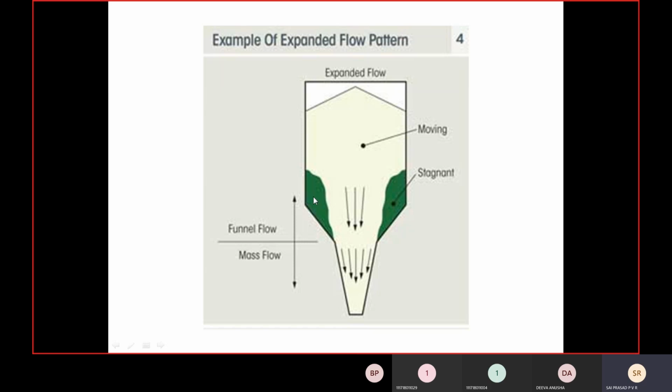If this angle is more, what will happen? Then the holding capacity of the solids in this particular region decreases. Suppose this line is like this and here you have an opening. At this point we will hold some amount of the solids, and because of it, we cannot create any movement in them. So if you have a sloping bottom and this angle is increasing, roughly greater than 90 and less than 180, say 140, all the solids will be free to flow.